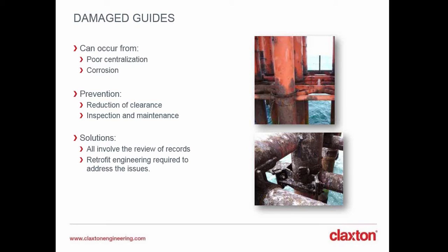As I say, it's quite a good indicator to check the condition of the cellar deck, as it might tell you that you should be checking your splash zone, because that's the area where it has the highest environmental loads, as well as a highly corrosive environment. So typically, it's one of the levels that suffers the most.